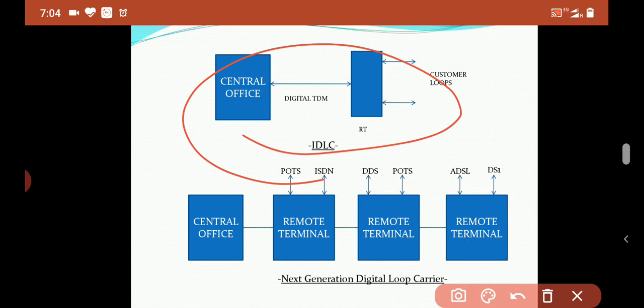Typically, direct digital connections are either DS1 or digital cross-connect switch signals. Therefore, a fiber-based DLC system is interfaced with the switch through multiplexing and demultiplexing equipment as some number of digital cross-connect signals. Functionally, the IDLC system is a distributed switching system where some line interfaces of the switch are moved to the remote location.